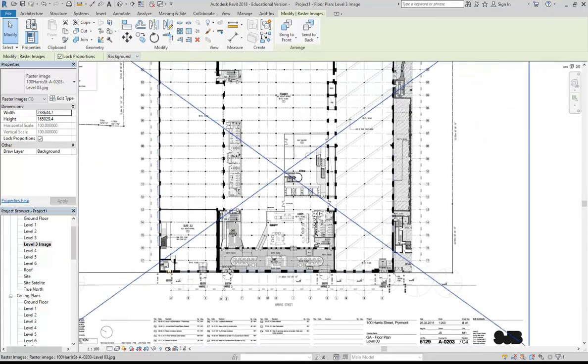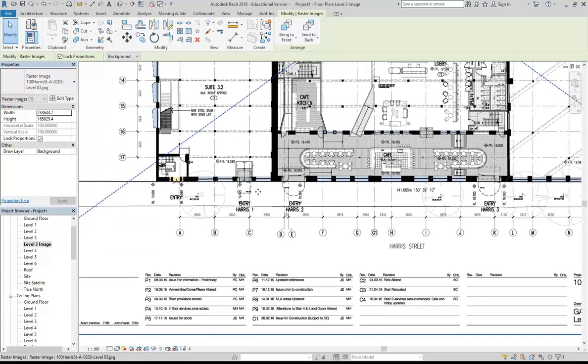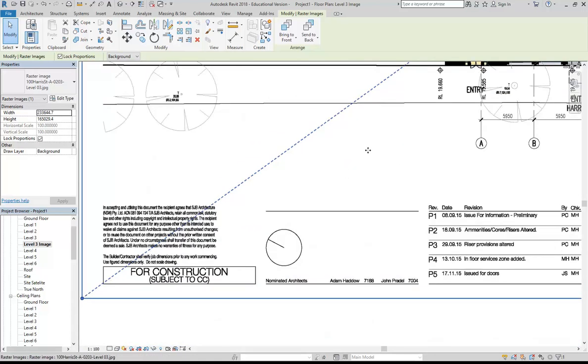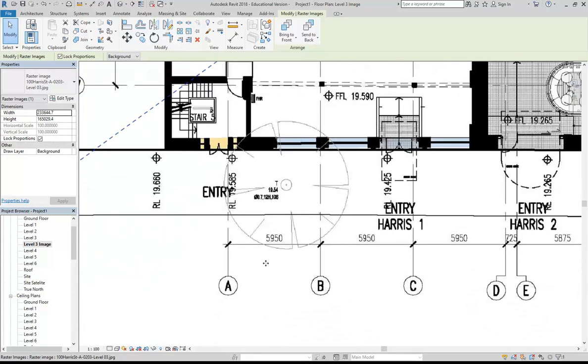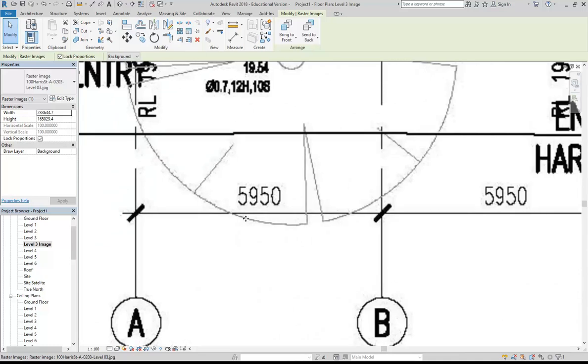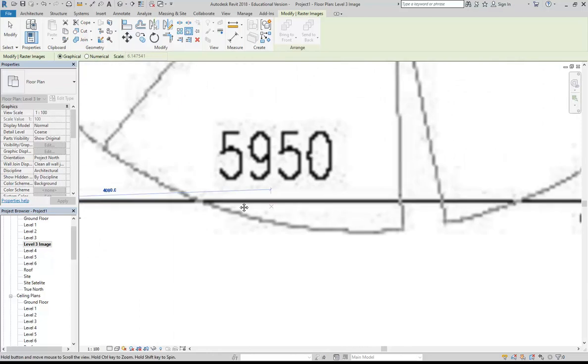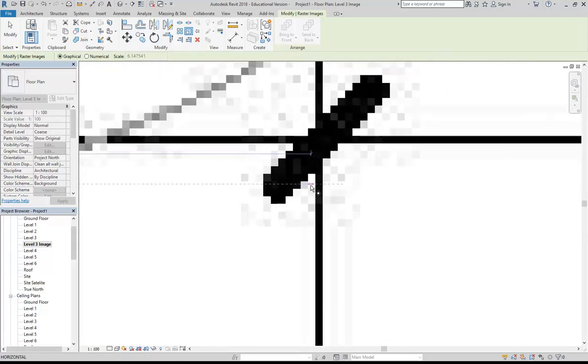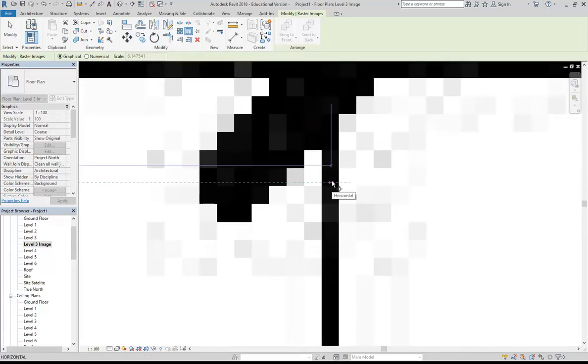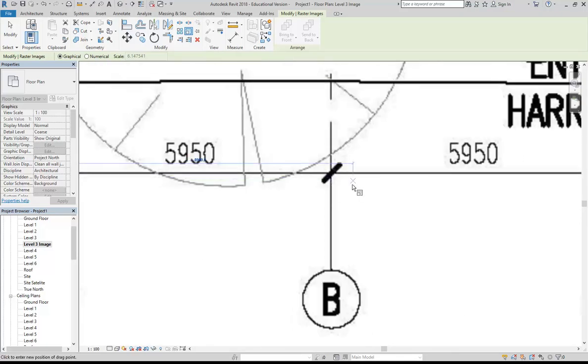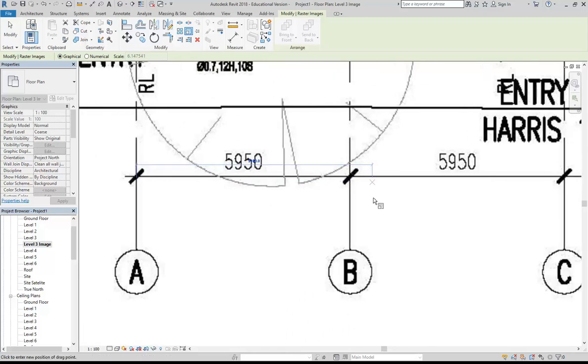And then we'll get a measurement and use that to scale it. If they've got a visual scale, that'd be nice, but really all we need is a dimension. So I've got my image selected. I'm going to click Scale. Remember, centre of the line, especially for Revit and AutoCAD drawings. So again, to centre, zooming in as far as you can is going to make it as accurate as possible. And then I'll type in that dimension I can see there, 5950.